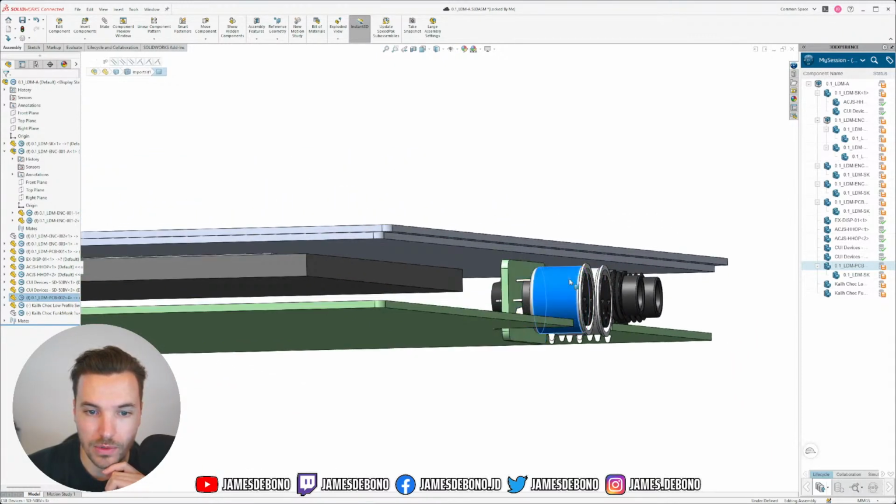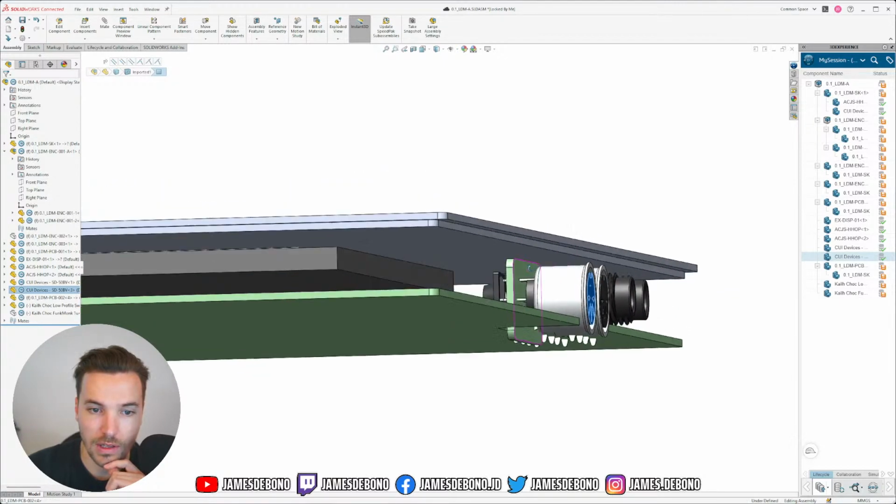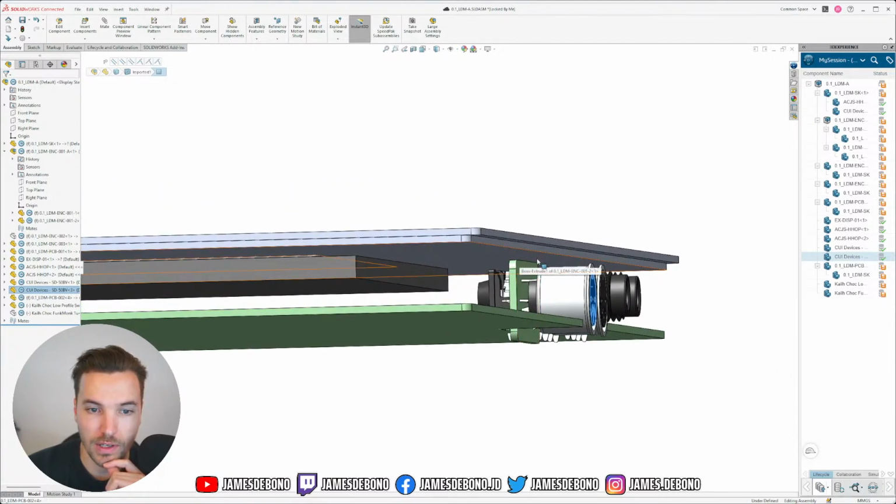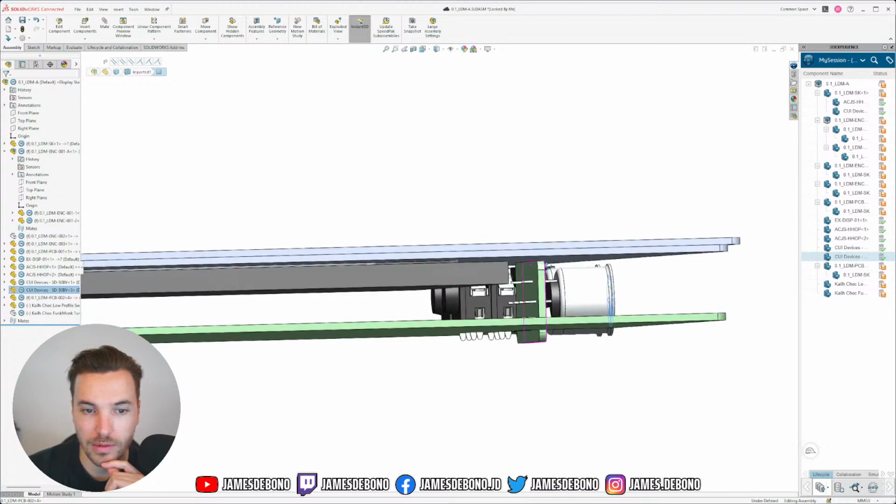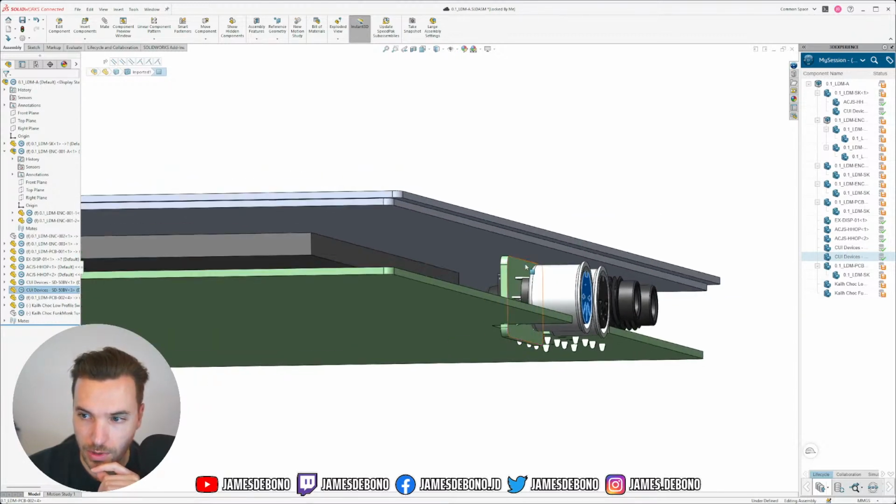So if I would then push on this jack in this direction, it wouldn't bend because it would be held in place by that slot. And same thing when you pull it out, it wouldn't bend that way because the slot would hold it in place. And that means that I don't have to have any extra fixtures or any extra soldering or anything like that. So this, I think, could be a really nice solution.